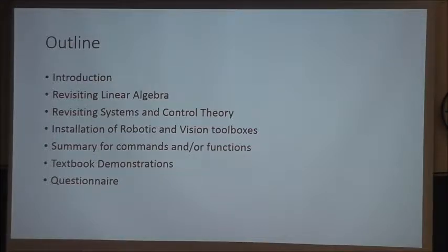By the way, we have different versions of the robotic toolbox and vision toolbox. If you click on the link in the textbook, you will see the robotic toolbox, versions 9.9 and 9.10. There is some conflict with the vision toolbox. If you work on 9.10 and do something based on Simulink and try to visualize your results, sometimes you can get an error, for example the parameter, object, or function doesn't execute in MATLAB.